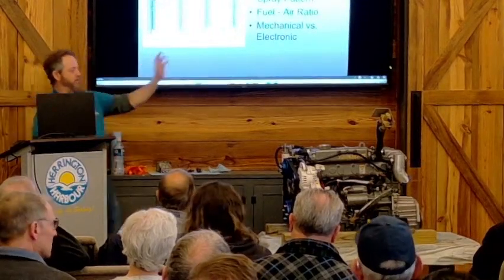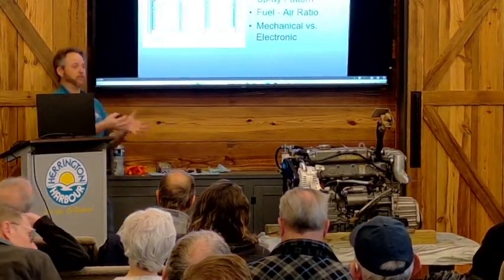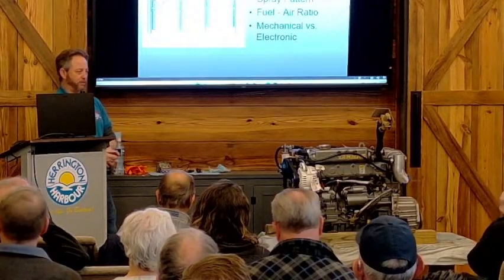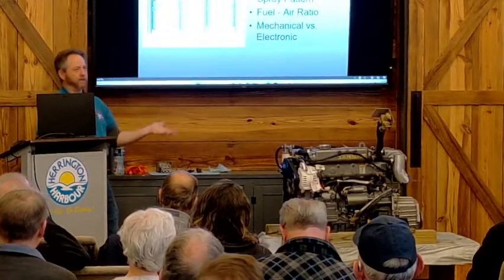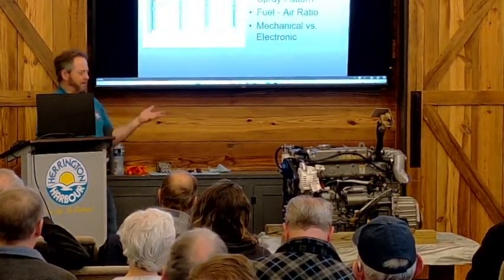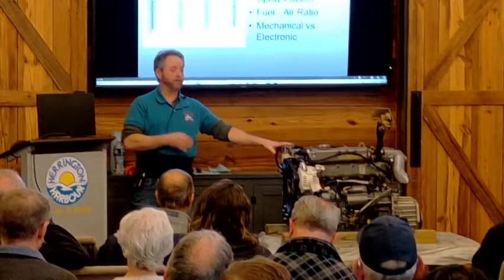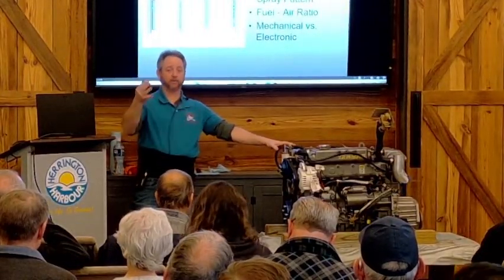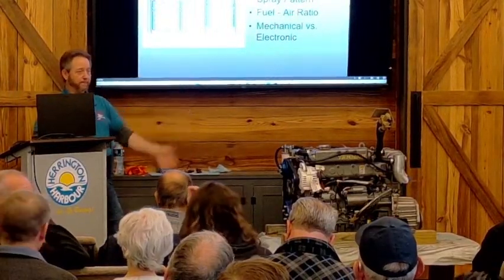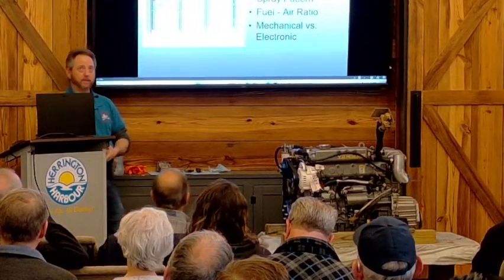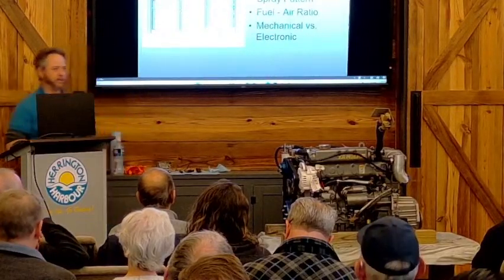Once you start throwing turbochargers and aftercoolers on, it becomes harder and harder to have the engine running clean because you're putting so much fuel into it. So pretty much anything under 100 horsepower can be a mechanical engine. With Yanmar's line, they jumped the gun. Everything below 30 horsepower is mechanical, and everything above 30 horsepower is electronic. So if you were to buy a brand new boat, after what year? I think 2014, 2015, they started using the computers on the Yanmars.